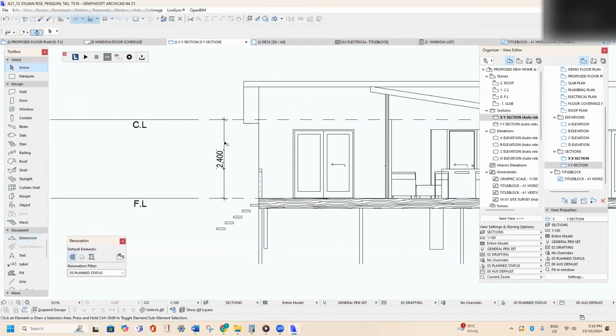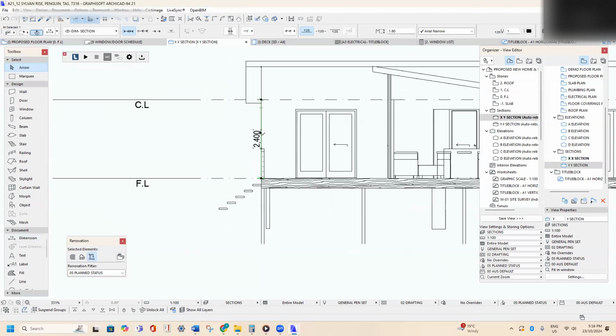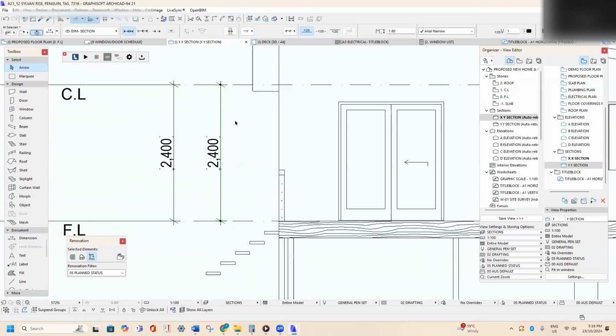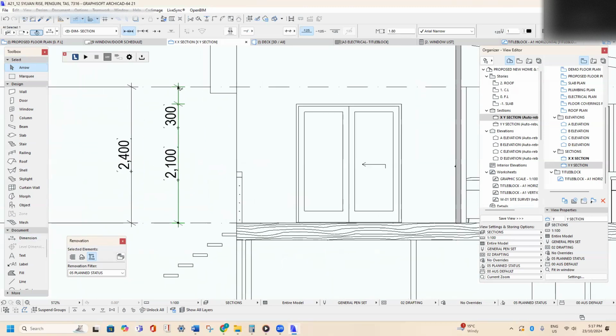both those lines, I normally drag the dimension over to the wall, and then I press Control D and press R, and I bring it 1 meter off. Control Shift D, R 800 to bring another one off. Then I'll click on this and hold the control button, and I'll click the top of the doors, and then I hold the control button and click the top to cut that away.